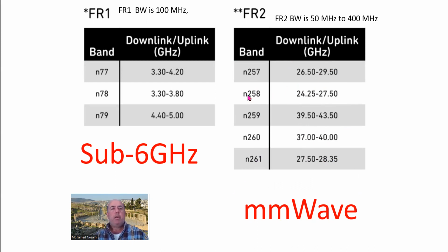Now, the difference between these systems is that for the upper frequencies here, the standard requires that you do beamforming with MIMO. For these ones here, you do MIMO. The intention in here is that the array antennas are intended for capacity increase, whereas here the use of beamforming is basically intended to optimize the coverage, so you can actually zoom in on users and increase the signal to noise ratio, so you can deliver higher data rates.